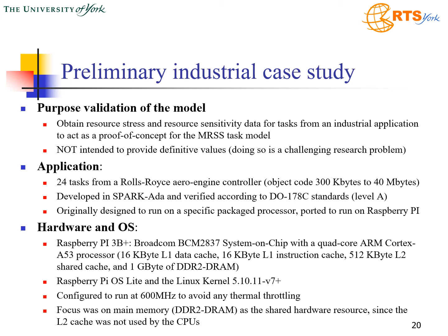The application comprised 24 tasks from a Rolls-Royce aero engine controller, with object code sizes between 300 kilobytes and 40 megabytes. This code was originally developed in Spark Ada and verified according to DO178C standards. It was originally designed to run on a specific packaged single-core processor, but has been ported to run on a Raspberry Pi. The hardware we used was a Raspberry Pi 3B Plus.